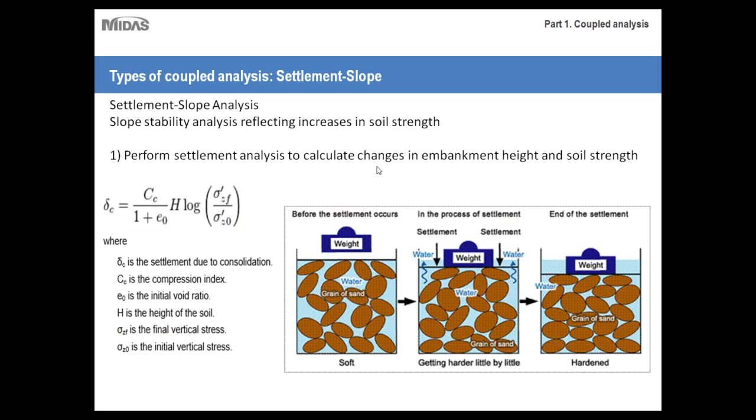Okay, and now let's talk about settlement analysis. Essentially, the first thing that we need to discuss is just the basic principles of settlement. I'm sure you're all familiar with consolidation, but just as a recap, consolidation is when, for example, you have a clayey soil that's subjected to a certain amount of weight. Now, because the pores in clay soil are so small, water takes a long time to escape from those pores when weight is pressed upon it.